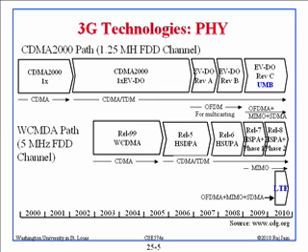Now it turns out CDMA has a problem with MIMO. CDMA cannot do as good MIMO as OFDMA can do. So basically that was one reason why they could not go to higher speed. CDMA has many limitations. Actually, I might have a slide later on which talks about CDMA versus OFDMA as to why CDMA has become the old technology. MIMO was difficult, but anyway, they put the MIMO here, so with MIMO we can increase the speed a little bit without giving up CDMA. But we really get good benefit of MIMO once we come to OFDMA. And I also use the word SDMA here, which I will explain later on, and here it says CDMA TDM.